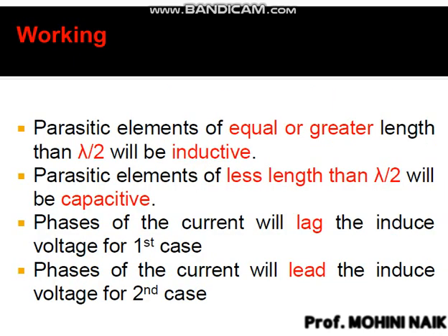Now there are two cases here. If the parasitic elements, that is the drivers, have length equal to or greater than lambda by 2, it will be inductive in nature. If it is less than lambda by 2, I am talking about the length of those elements, it will be capacitive.